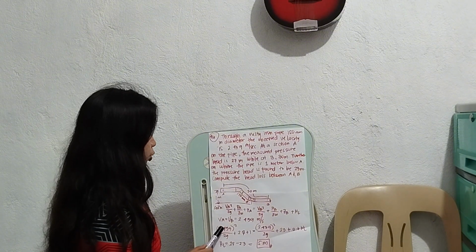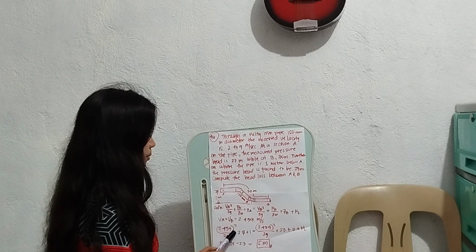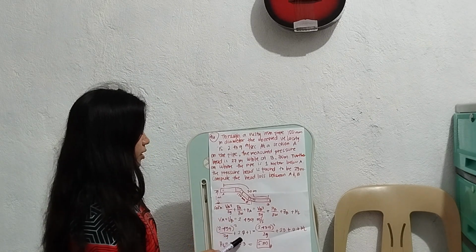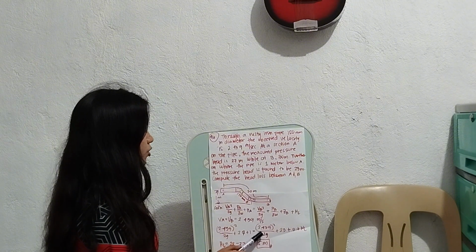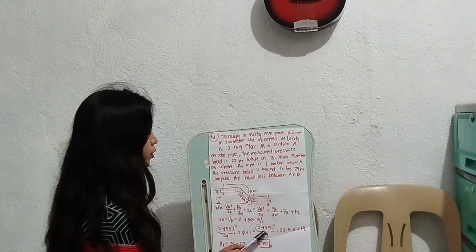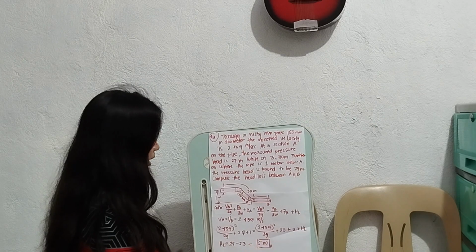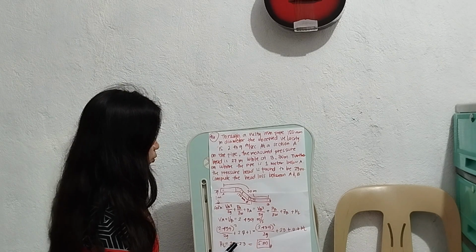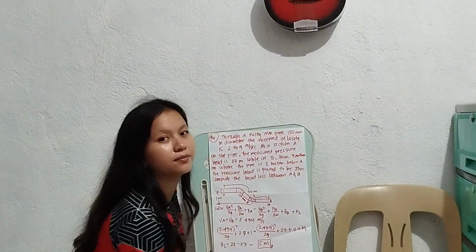Then 2.439 squared over 2g plus the pressure head 27 plus the ZA which is 1 equals VB 2.439 squared over 2g plus 23 plus 0 plus the head loss. So the head loss equals 28 minus 23, which is equal to 5 meters.